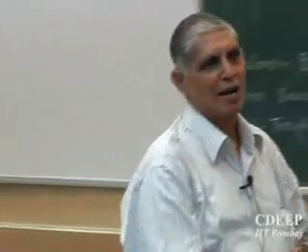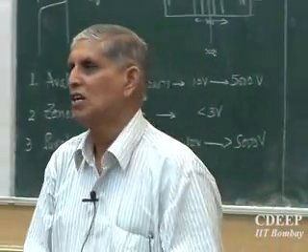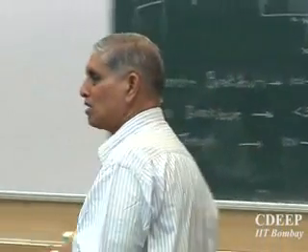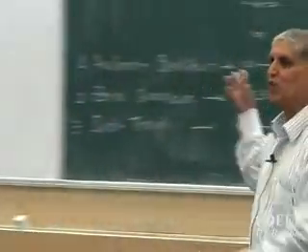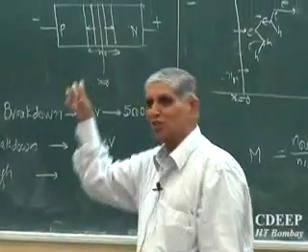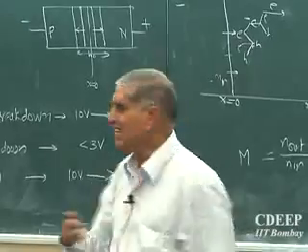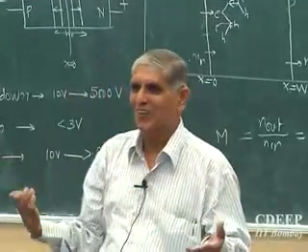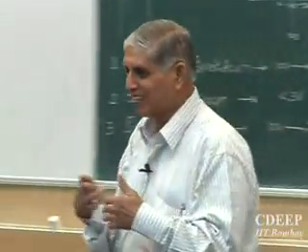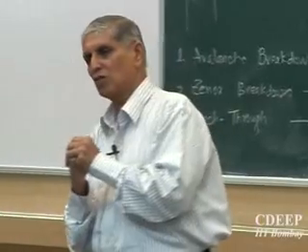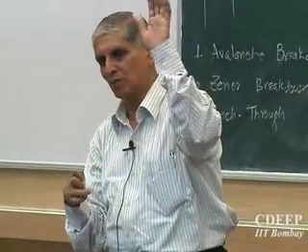Let's say its avalanche breakdown is 1000 volts. So you are not allowed to go beyond 700 volts. Okay, 70% derating is the safety margin for all electrical engineers. So don't say, oh, you said it was 1000. No, 1000 is because this is all probability issues. One doesn't want to say exactly how much the doping is in every device, every place. So derated values are always 70% of the maximum specified.